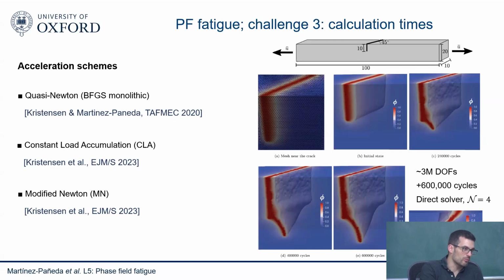You can use iterative solvers. Again, when the problem is more linear, more simple, they work very nicely if you find a good preconditioner. But when you want to do the exciting stuff, the corrosion and fatigue, the plasticity and fatigue, then it becomes complicated to handle those. So I guess the good news is that there are lots of things you can do. People are also working on adaptive mesh refinement. There are so many other things that one can do. But those seem to work well for the easier problems, which are linear elastic and so on. For the difficult problems, you need to do almost cycle by cycle, and that's the problem, I think.